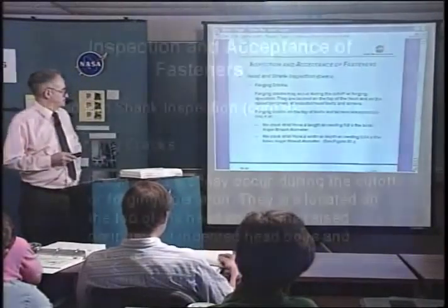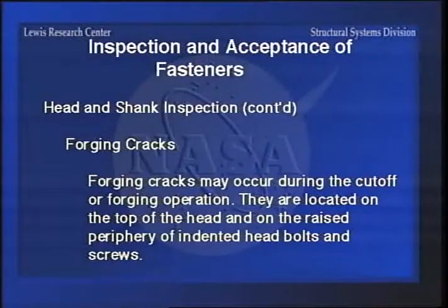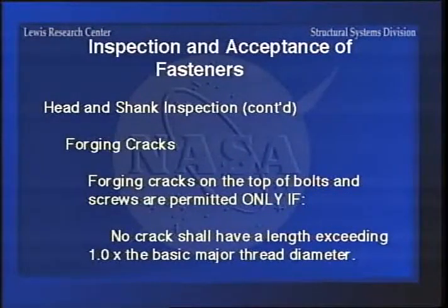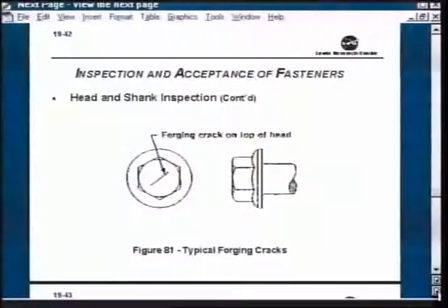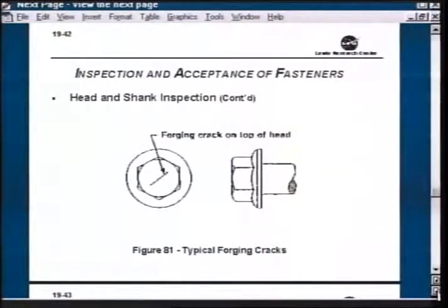And you can accept some of them if they are very, very slight, so that they're more or less a streak rather than a crack, just an indentation mark, as long as they have a very shallow depth. But once again, it depends on the criticality of the installation as to how much you accept in the cracks. Here's one that shows a forging crack on the top of the head.